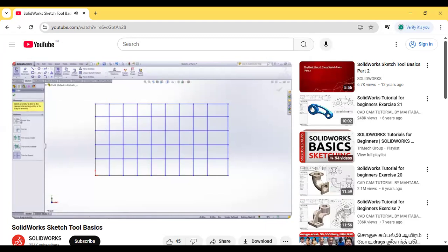The trim tool, which can be found under the Sketch tab or by going under Tools and then Sketch Tools, is very useful for removing segments of lines that are unnecessary. In the Property Manager for this tool, there are 5 different options. To use Power Trim, click and hold the cursor starting away from the entities, and then move your cursor over the entities to be trimmed. If you remove a line that you want to save, move your cursor over the red square to add that line again. The Corner tool allows you to pick 2 lines and extend or trim them to form a corner. This tool only works if the 2 lines either intersect or would intersect each other if they were extended.